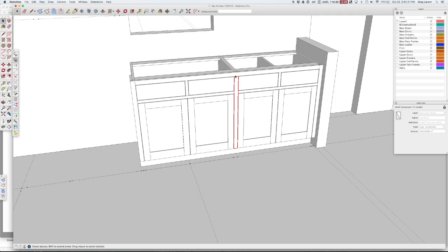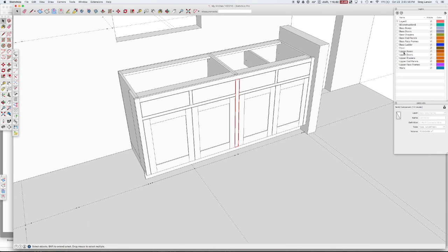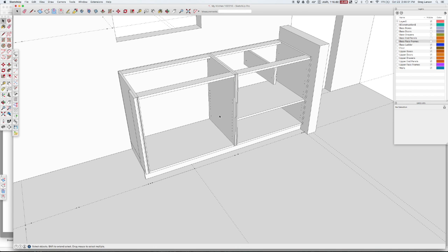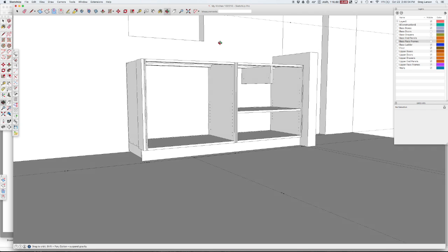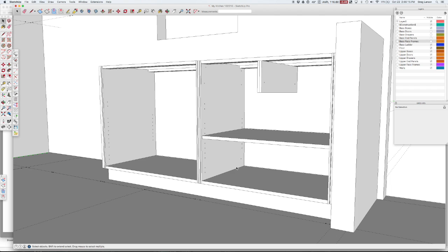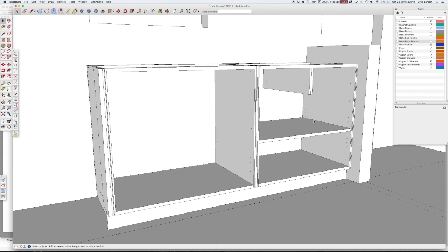Now a connector style, basically that's the style that just covers the transition between the 2 cabinets, but we get something additional. And if we turn off all of our doors, drawers, end panels, and face frames, you'll see these extra holes up here. There's 1, 2, and 3. What those are called are connector holes. And you see them going through on this side as well. And they are specified in this case as 5mm holes that go all the way through the part.